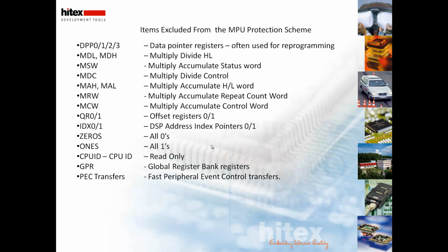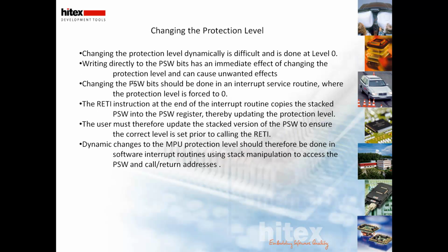Some, however, are excluded, so these are the ones that you'd expect. The data pointers, for example, so level 1, 2 and 3 code may use indexing and require the data pointers. Similarly, the hardware MAC unit and all the registers associated with that, and also things like PEC transfers, which could be going on that you don't want to be adversely affected. So all the common sense registers, if you like, are excluded from the protection scheme.